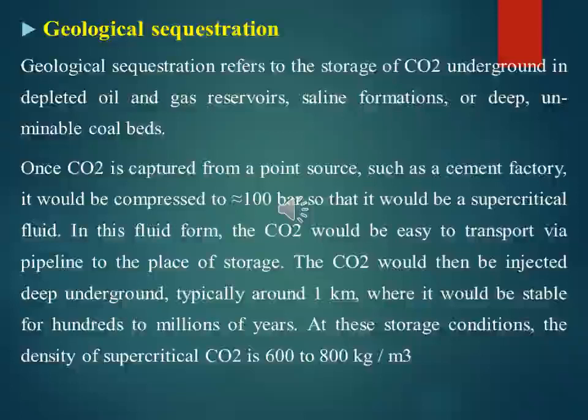The porous rock must be capped by a layer of low permeability which acts as a seal or cap rock for the carbon dioxide. Shale is an example of a very good cap rock, with a permeability of 10^-5 or 10^-9 Darcy. Once injected, the carbon dioxide plume will rise via buoyant forces since it is less dense than its surroundings.